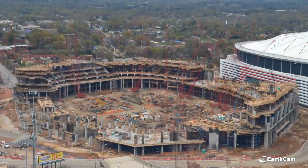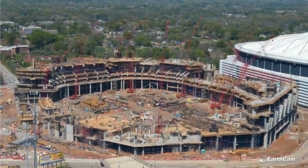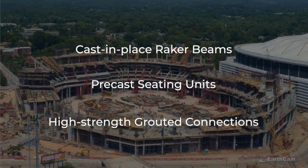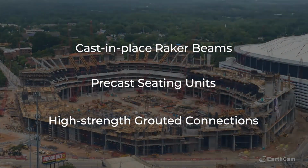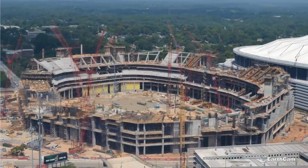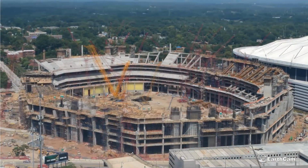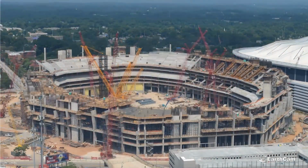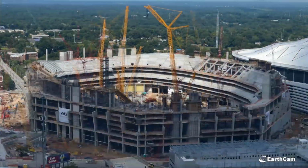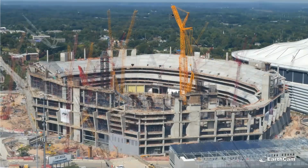The concrete bowl structure of the Mercedes-Benz Stadium exemplifies a carefully coordinated system involving cast-in-place racker beams, precast seating units, and high-strength grouted connections. Together, these elements achieve both excellent visibility for spectators and high structural integrity, making it an ideal model for large-scale stadium design.